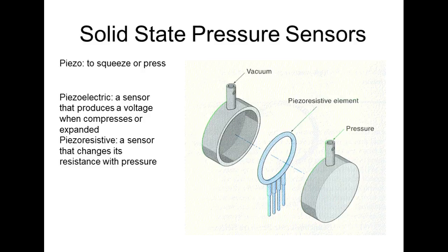You come down and you pop it, that thing comes down and hits the piezoelectric crystal, and as long as you got your thumb on there, that pressure is still being applied to the crystal. It's not generating a voltage with pressure, it's generating with the change of pressure, right? So piezoelectric works really well where you want to see a pressure change. But anytime the pressure is not changing, a piezoelectric would not put out a voltage.